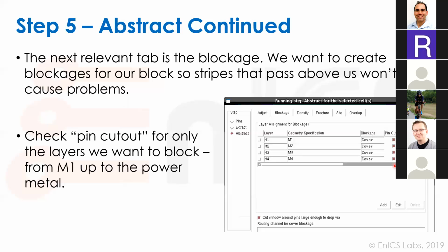One more thing, you mentioned here, for the metals, doing cover blockage. Does it mean there is a single statement in the LEF with the blockage, or beyond it there are multiple other patches? Because these patches are slowing down the tool unnecessarily.